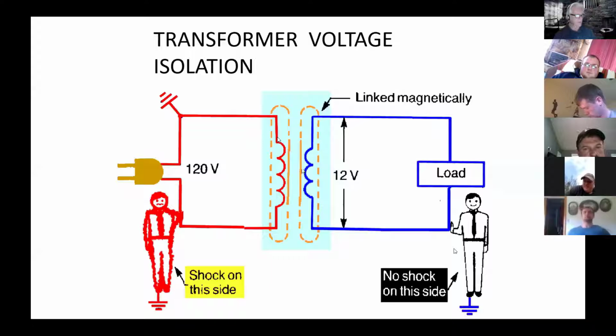And if we design an amp specifically for that purpose, so that it's operating at max saturation, then if I get a spike like lightning, or somebody kicks on a motor that would cause a little spike in the line, it can't get transmitted to the secondary because this is already passing all the voltage that it can pass. Any excess voltage it just can't, it's clamped.